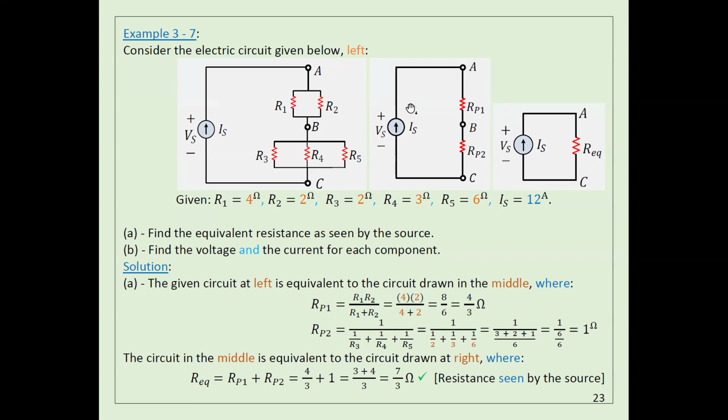You can see this one is in parallel with these two. So the voltage across this current source is equal to the voltage across this one. And these are in series, so if I want the voltage between A and C, I need to get the voltage here plus the voltage here. Got what I'm saying? Now I already got the voltage here.